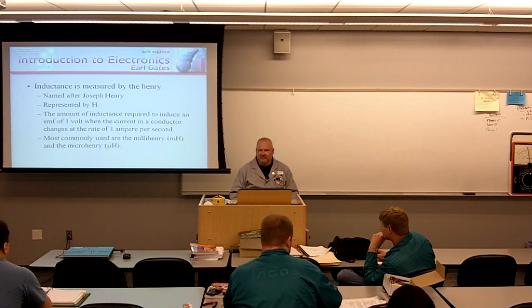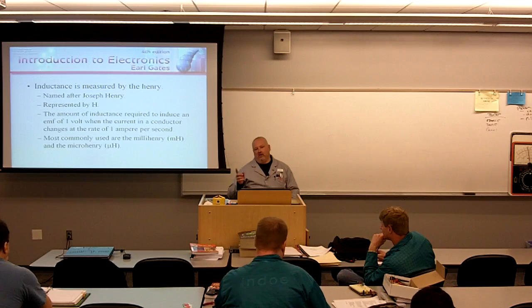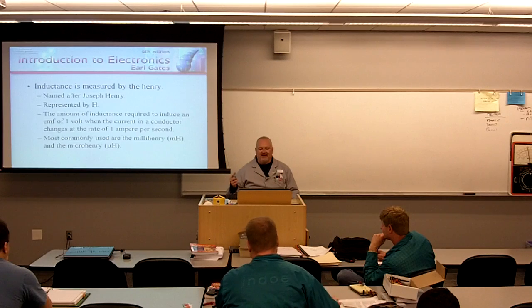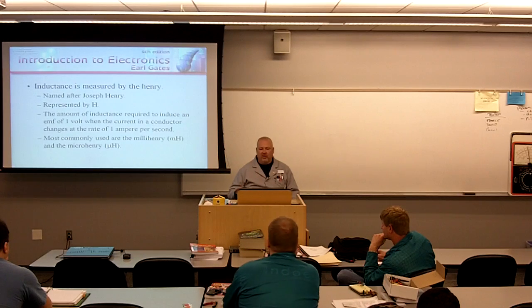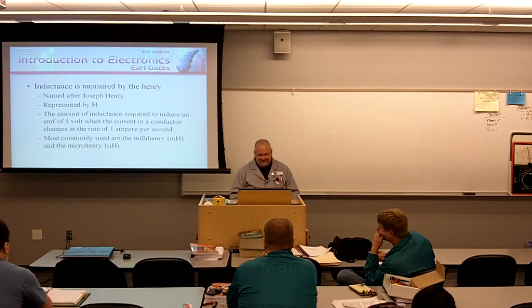Henry, ironically, is abbreviated with the letter H. And 1 Henry is the amount of inductance required to induce an EMF of 1 volt when the current in the conductor changes at a rate of 1 amp per second. So 1 Henry is equal to 1 volt of EMF at 1 amp per second. 1 H is equal to 1 volt over 1 amp per second.